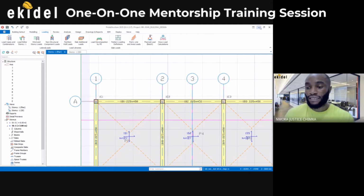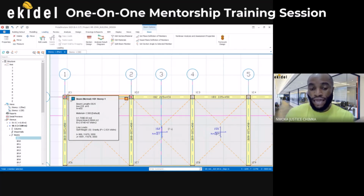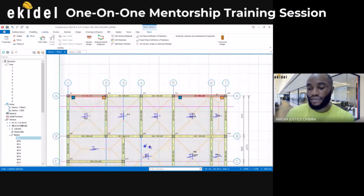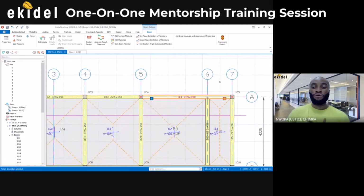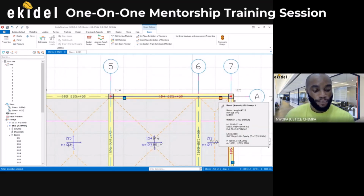Now, by default, this software takes everything as fixed end, like all the ends of beam as fixed ends. Which in my own case, I used to apply all the ends of the beam to be hinged. That's pin. Right?